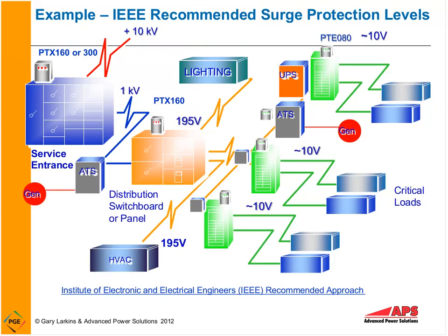And I've shown you on this slide an example from the Institute of Electrical and Electronics Engineers. This is an example of the many modes or levels of surge suppression that they recommend in a facility to help protect against the transient overvoltages or power surges we talk about. And those are sub-cycles, so very short, brief duration, requires a specific power quality monitor to see them. These are very short-term anomalies in the system that can cause malfunctions or equipment breakdowns.